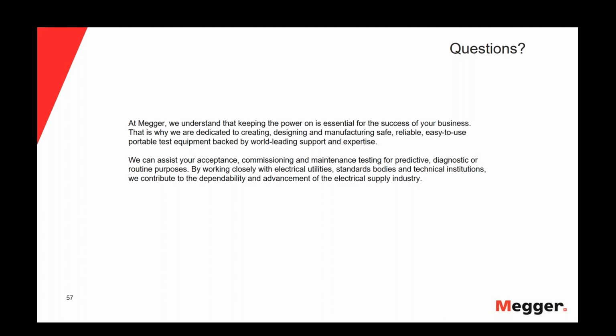There has been one other method used to specifically determine the amount of water tree growing in cables, and that was the isolation relaxation current method, which was used in certain parts of the world very successfully, but never caught on over here in the North American market. But overall, Tan Delta is the state-of-the-art method to really get the aging condition.